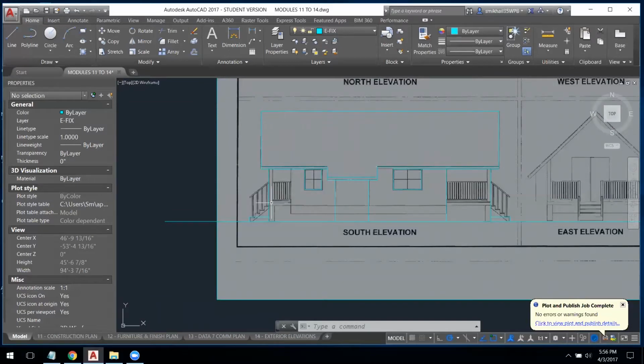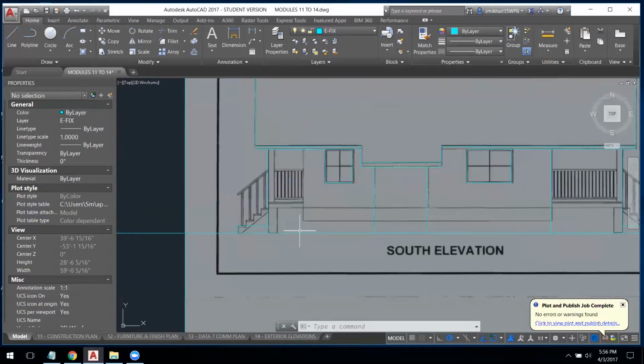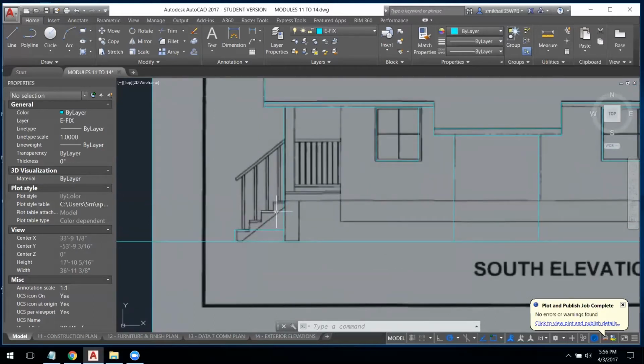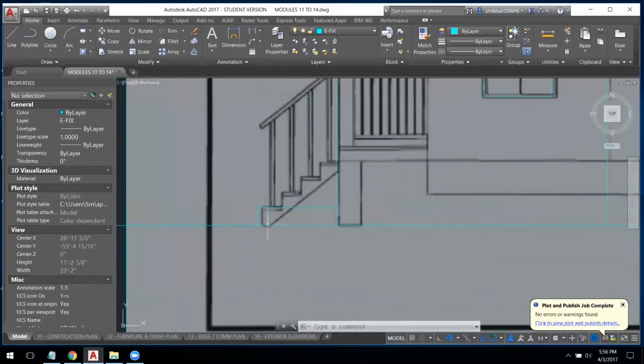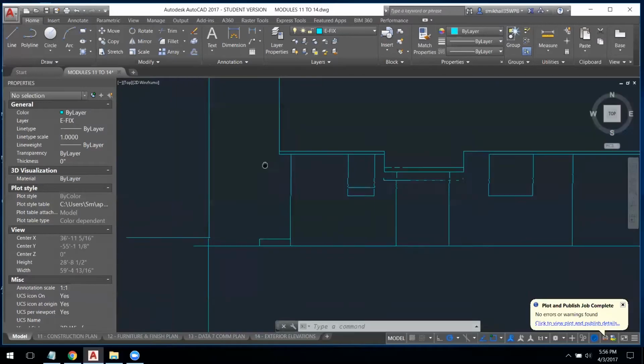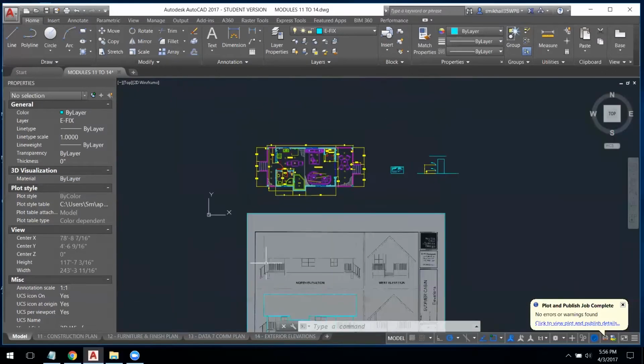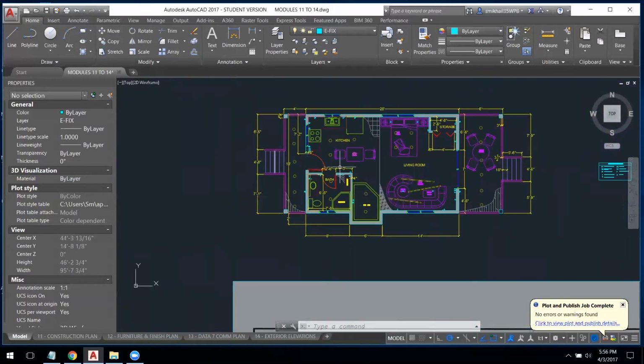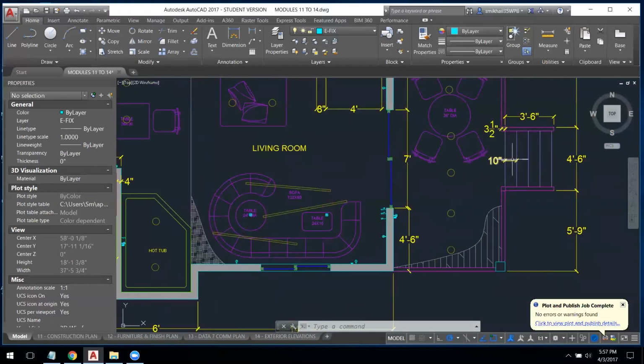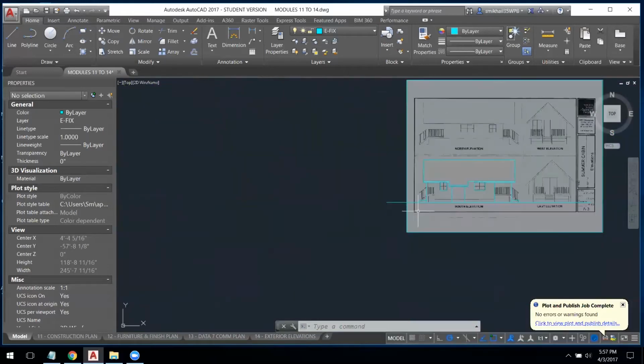Okay, we have a few horizontal datums that I can just copy over, and then the vertical ones that are remaining are the thicknesses of the columns as well as the widths of the treads. So we'll take the width of the tread. I'm going to go back into my floor plan and double check what this width is. And we annotated it before that it's 10 inches. That is the width of the step.